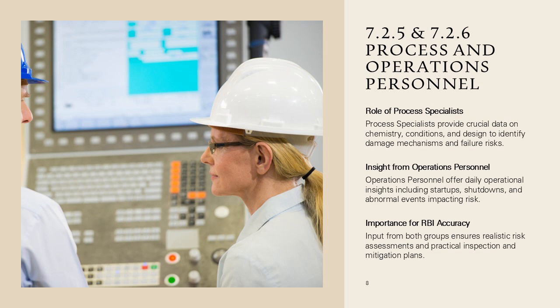They often identify issues not captured in formal documentation, such as recurring operational challenges or informal practices that influence risk. API RP 580 highlights that without input from process and operations personnel, RBI assessments may rely on idealized assumptions that do not reflect real operating conditions. Their participation helps ensure that risk estimates are realistic and that inspection and mitigation plans are practical and implementable within